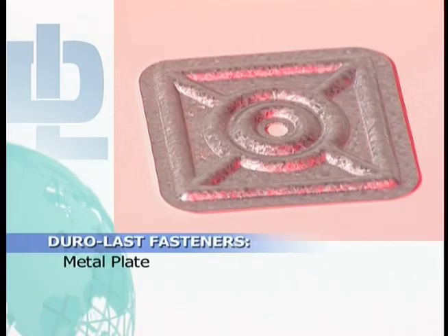The Duro-Last square metal plate is designed to be used with all Duro-Last deck fasteners except the auger fastener. This is a 3-inch by 3-inch square galvalume plate. Square metal plates may be used for installing insulation, fastening around all penetrations, between the tabs on sheet edges that are perpendicular to the tabs, and on all parapet wall fastening. The stress distribution plate should be installed with the edge a minimum of 1/4 inch from a factory weld.